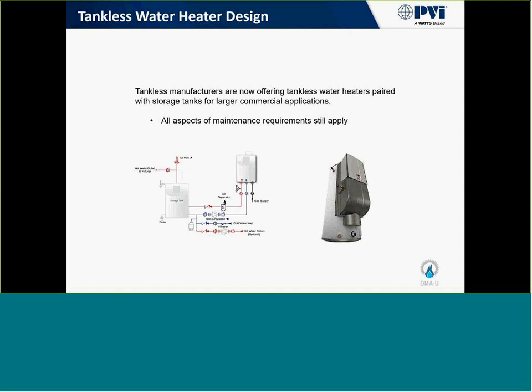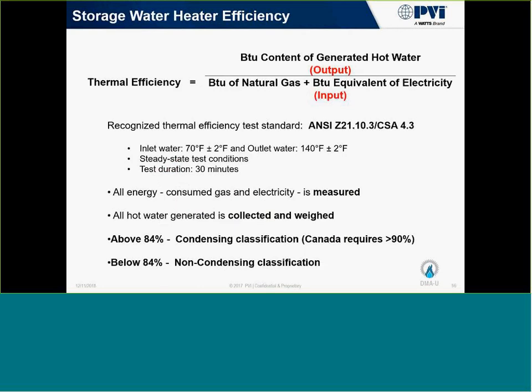There's a pretty steady preventative maintenance type scheduling that needs to be in place, from a best management practice of that facility, in order to protect those heat exchangers. That does not change no matter what you put in that system with regard to storage or non-storage with tankless water heaters.